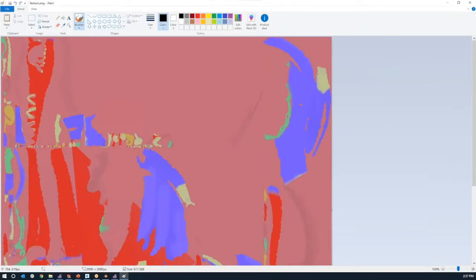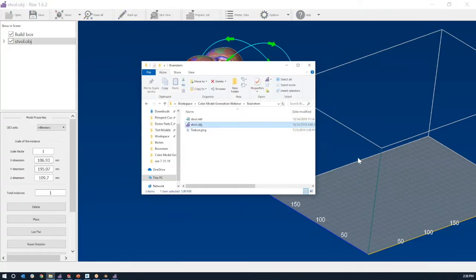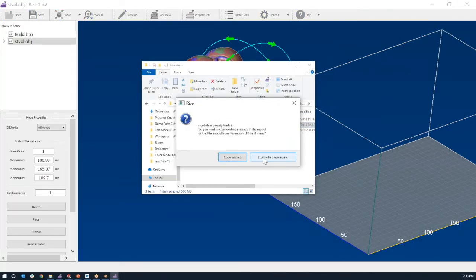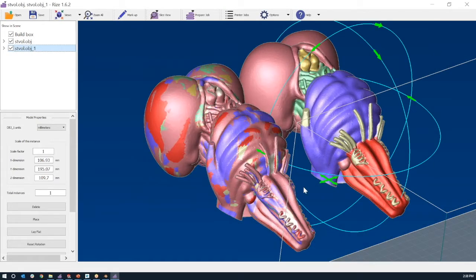I've sometimes encountered this, not with this particular file, but basically it jumbles all of the references up so that nothing is colored correctly, but all it takes is rotating this part. Now it's good. If I add this as a new file, now you can see all of the correct colors.